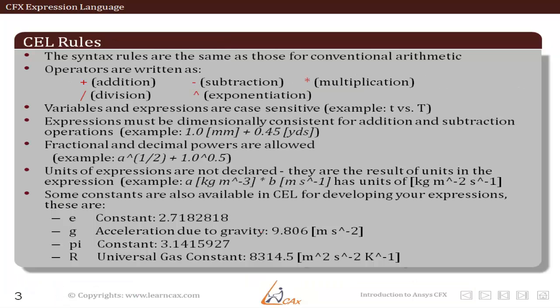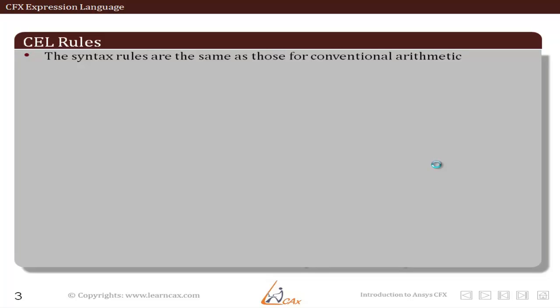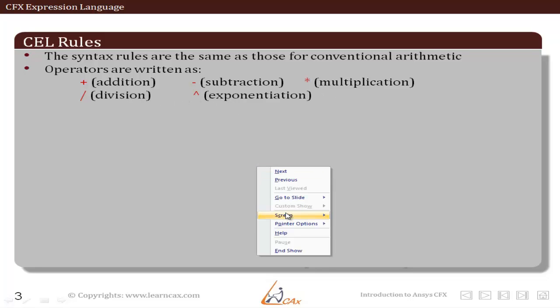There are certain rules of the CFX expression language which need to be followed in order to create expressions. Let us list them one by one. The syntax rules are the same as those for conventional arithmetic. Operations that are allowed are addition, subtraction, multiplication, division, and exponential.